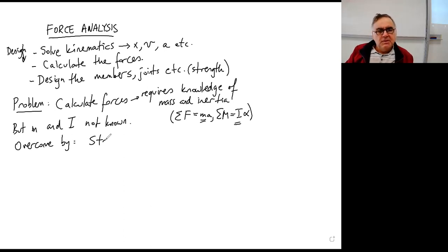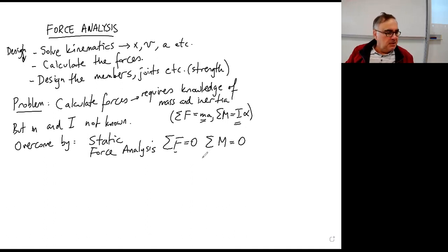It will be an approximate thing, but we first do static force analysis. What does this mean? Static force analysis means you either assume that the accelerations are zero or very close to zero. The summation of forces is zero. Summation of moments is zero. Which means that either M is very close to zero, or I is zero, or alpha is.